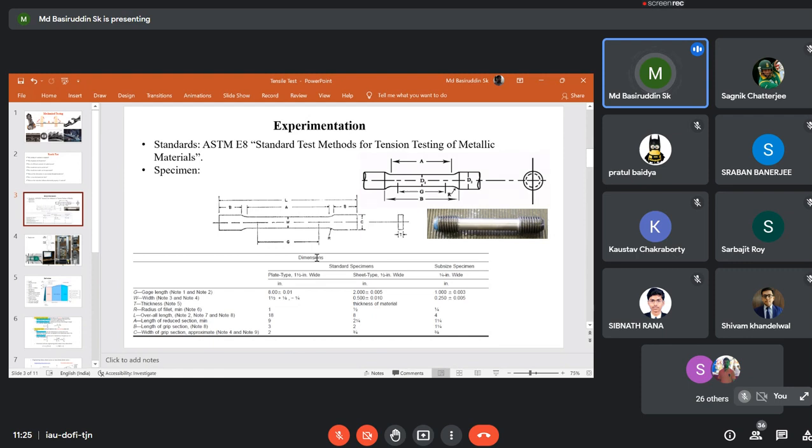But if you are intentionally creating local regions where you want the deformation to be restricted, then you will not get the strength versus elongation graph as per the materials you studied earlier, where no notches were there. So that is the thing you need to keep in mind.